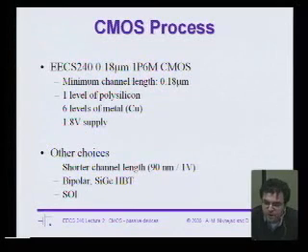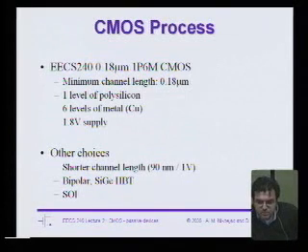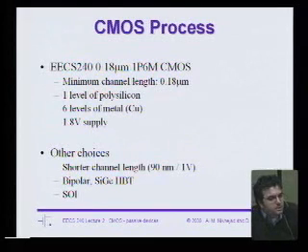Okay, I know some of you guys in here have actually worked in industry, so you have some good insights into this. Yes? The initial barrier is too high these days, with nanometer processes. Yeah, that's part of it. So how much does it actually cost to fabricate a CMOS 90 nanometer chip? How much do you have to pay for the masks? It's about $1 million, right? Give or take. It's a lot of money.